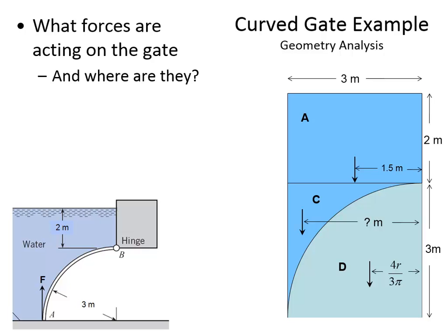And so I'm putting in the formula for its distance from the edge to the center of area. And if I do that calculation, that works out to 1.27324 meters. And then add 1.9314 meters squared times the unknown distance x, CP of C. So it's an area weighted average.